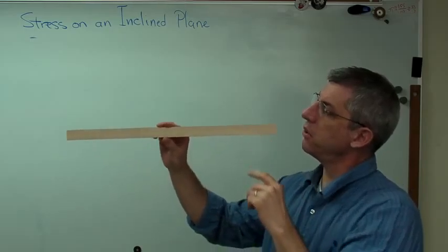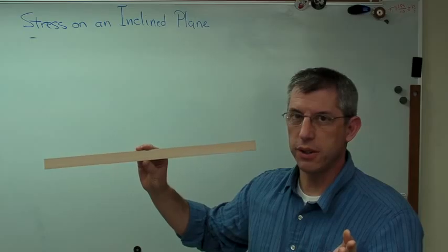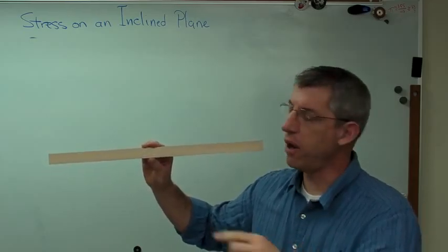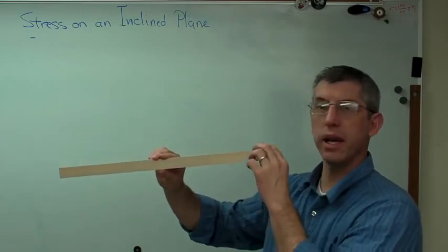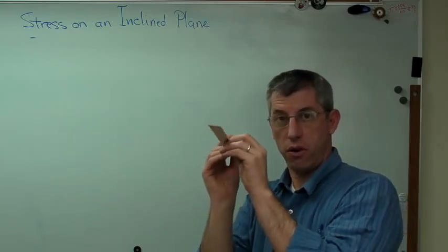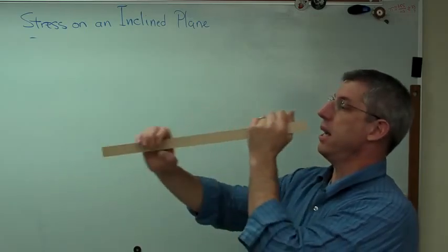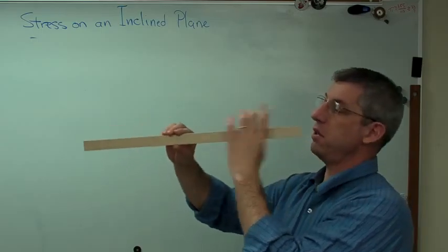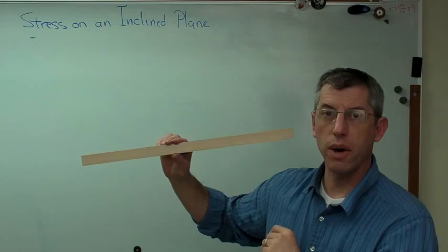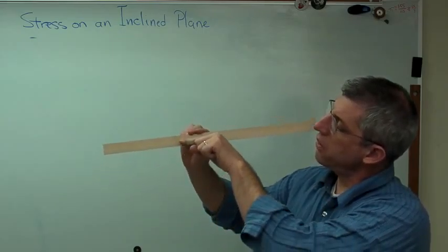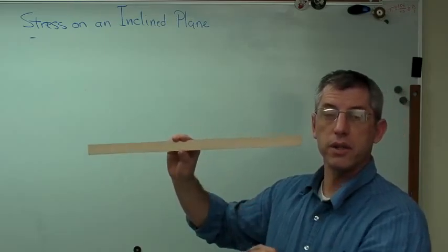So let's say I put a little strain sensor. Let's say I've got a magical stress sensor. Now, as far as I know, there is no such thing as a stress sensor, but let's just say I've got one. And it looks this direction. It's going to see a certain number, whatever this is. It's going to be like force divided by the cross-sectional area. Well, what if I put the sensor on that way and pull? Well, it isn't going to see anything. Now, there may be some strain this way because of Poisson's ratio, but there won't be any stress that way. So that stands to reason if stress is zero that way and some big number that way, it must be other things at other directions.